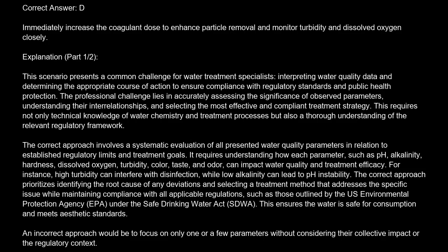The correct answer is D. Immediately increase the coagulant dose to enhance particle removal and monitor turbidity and dissolved oxygen closely. Explanation. This scenario presents a common challenge for water treatment specialists: interpreting water quality data and determining the appropriate course of action to ensure compliance with regulatory standards and public health protection.